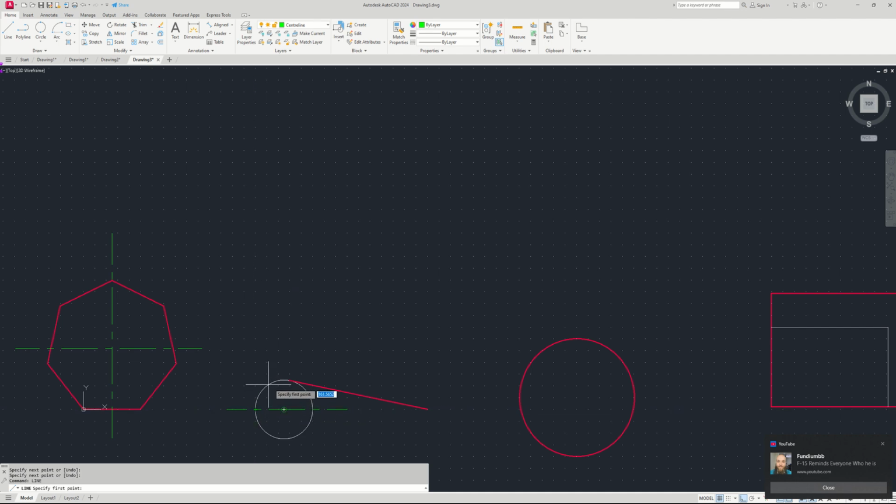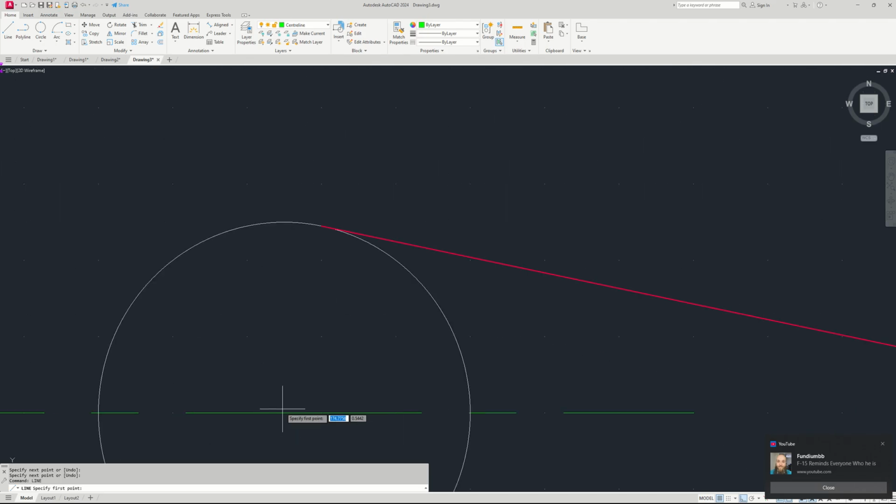Now hover it again over the circle, then the center highlights. So move gently to the center. The green here is the middle of the center line, the green triangle, but that's not what I want. Let me just set my cursor slightly over the circle. Now where the plus is, is the actual center of this circle, so I can draw a new line over there.